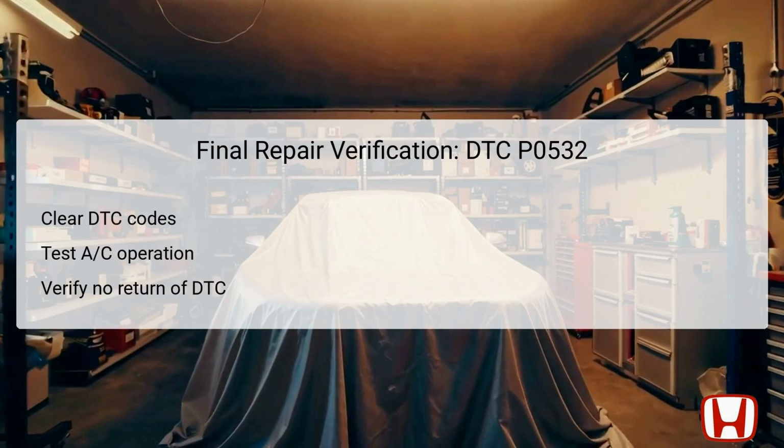After completing the necessary repairs associated with DTC P0532, it's crucial to perform a final verification to ensure that the issue has been resolved. Start by clearing all DTC codes using the HDS tool, which allows the system to reset and eliminate any stored error codes.